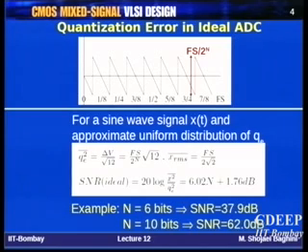And if you just calculate, it is very easy because everything is just a function of n. There is nothing else here, and full scale will get cancelled. Therefore, it is independent of full scale. So, maximum SNR will be 6.02 n. The 6 is actually 20 log 2. That is the reason it appears as 6 plus 1.76 dB.